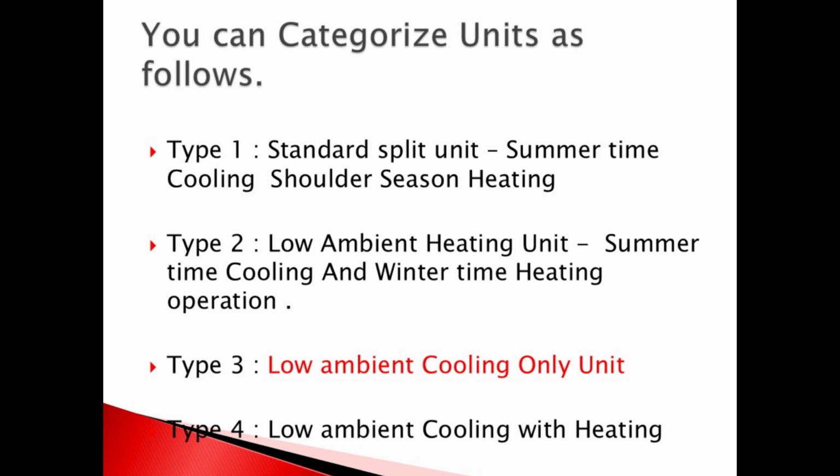In these cases, we typically use cooling-only units. Other examples where winter cooling is needed include garbage rooms, mechanical rooms, and elevator machine rooms. This unit is rated for minus 40 degrees centigrade, and windscreens and a stand for the outdoor unit are a must.